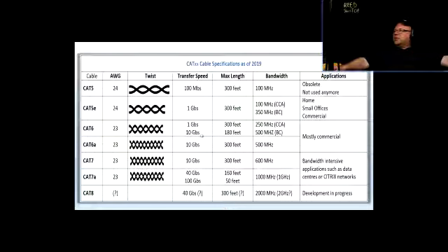So it is important to know. Somebody wants Cat 6, and you say, okay, how long are your runs going to be? If they're like 250 feet, you know what? You might as well get Cat 5e, because you're just going to pay for nothing, right? You're not going to get any benefits out of that, unless you're trying to get the analog transmission. Okay. So again, the maximum distance is 300 feet, but if it's 10 gigabits per second, now up to 180 feet.